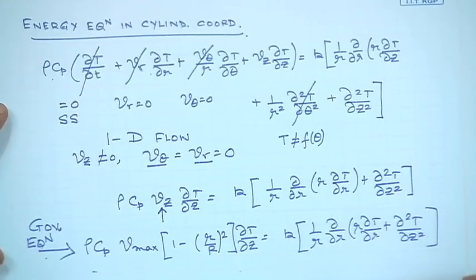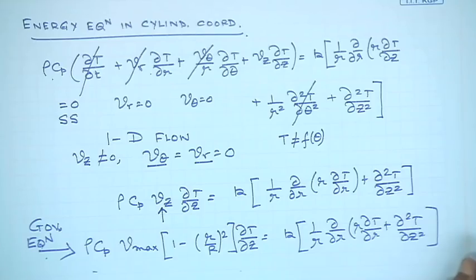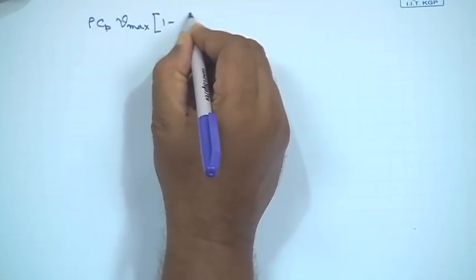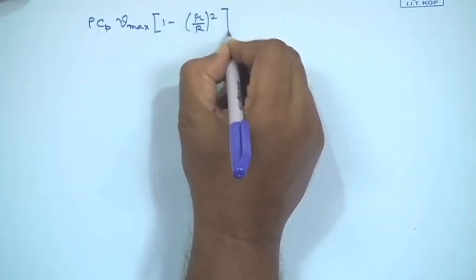So, this underscores the utility of energy equation in dealing with any problem of heat transfer, energy transfer, work done in any process. I have neglected any viscous dissipation in the formulation, and I have also assumed that there is no heat generation in the fluid, in the liquid itself. So, this is my governing equation which I now need to solve with appropriate boundary conditions. So, let us see how it can be solved, or what other simplifications I can make in order to solve this equation.